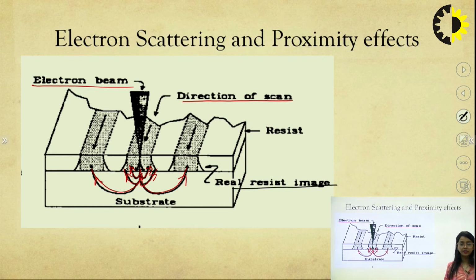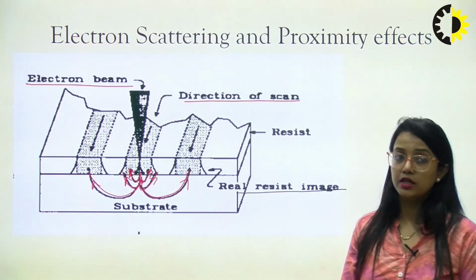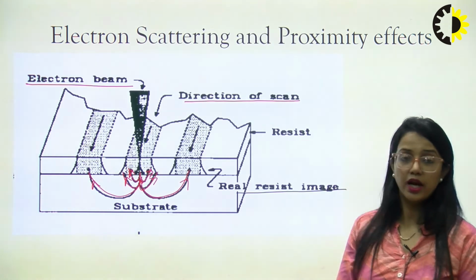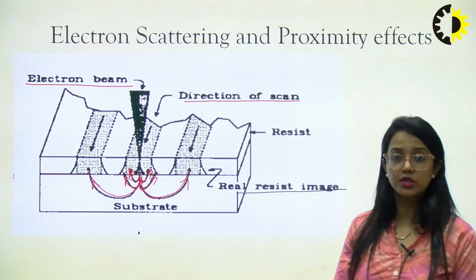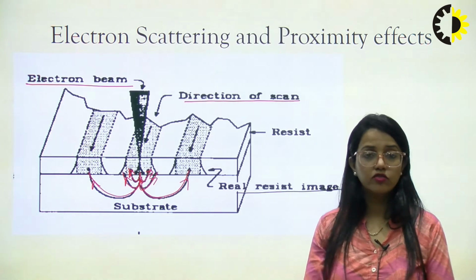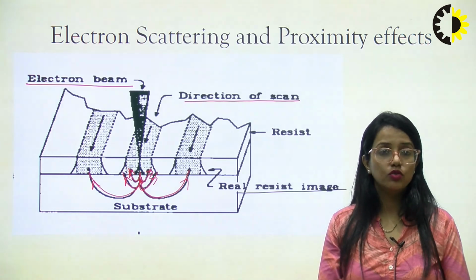Depending upon the scan, or depending upon the reticle which is available to the control system, the electron scattering will only take place at the point where the electron beam is focused, and the electron beam will be focused only at the point where the required N well or P well needs to be created.